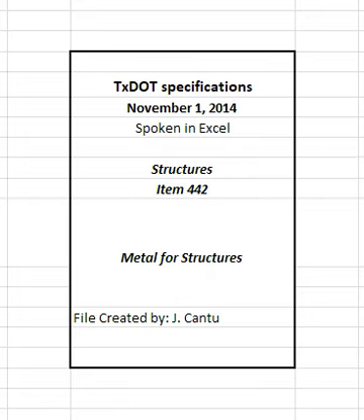ASTM A529 grade 50. ASTM A572 grade 50 or 55. ASTM A588. ASTM A709 grade 50, 50S, 50W, or HPS 50W, or ASTM A992. Specify ASTM A6 supplemental requirement S18, maximum tensile strength, for material used for sign, signal, and luminaire supports.